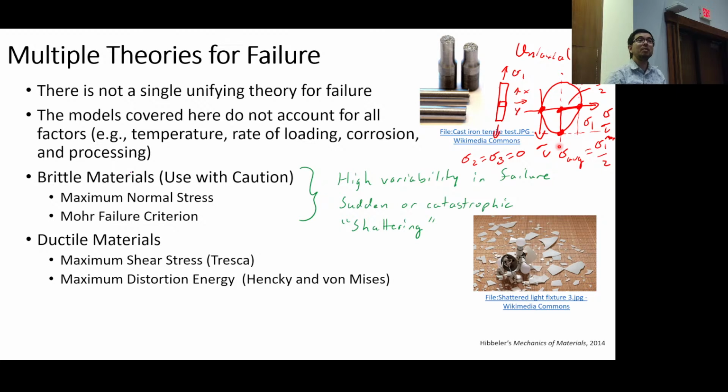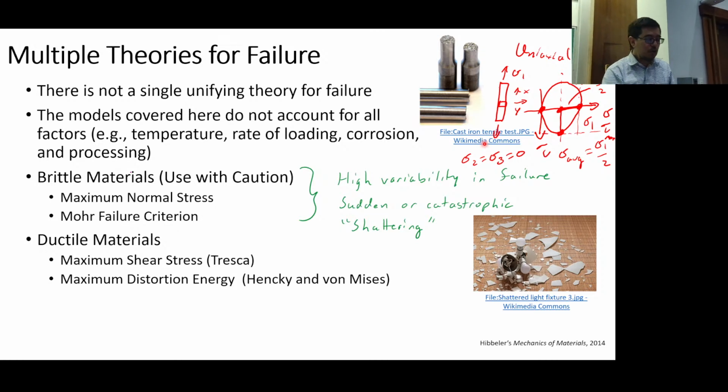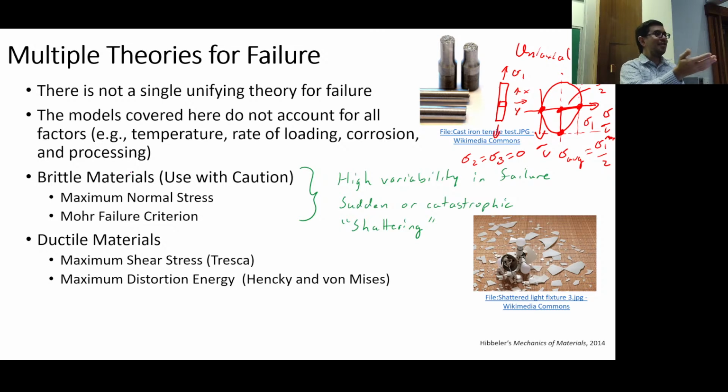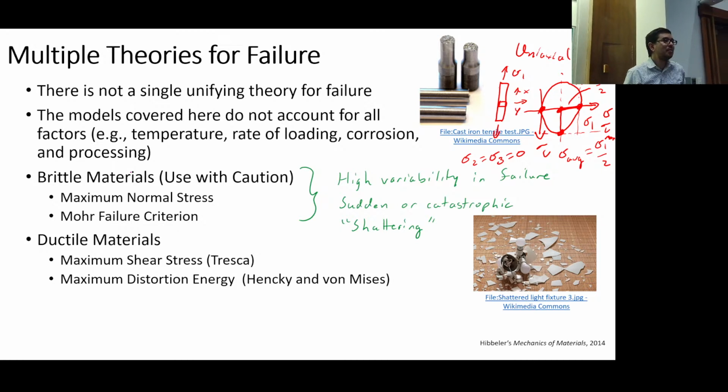Or you just remember, it's going to be whatever the yield strength is divided by 2. Why did I say that? You just said sigma 1 over 2, so why did I say yield strength divided by 2? Well, the yield strength is how the material would fail if you're doing it this way, but we know it fails at half of that in shear.